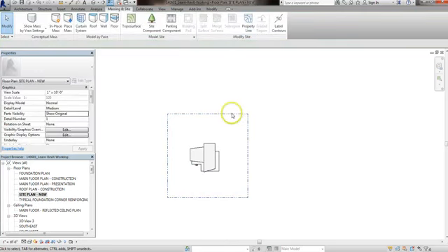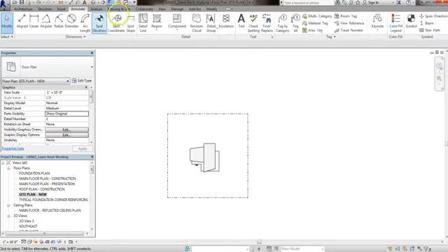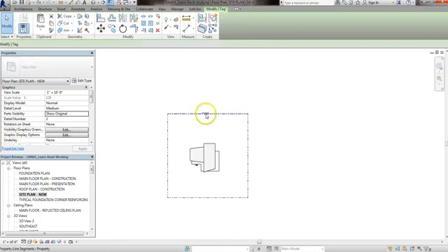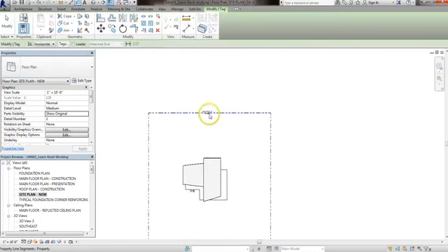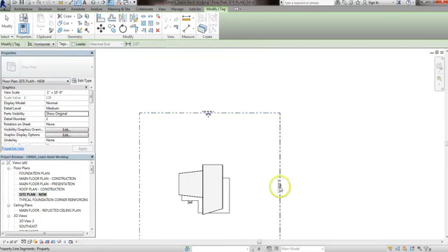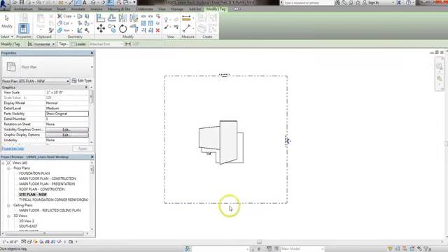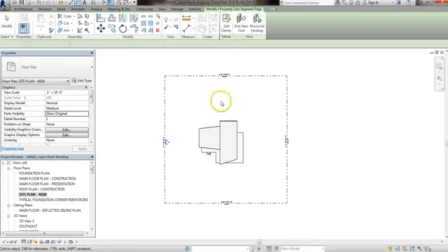So now we have our property lines. And then we're going to annotate them. We're going to tag them. We don't need the leader. Now I can tag them. So if you guys had the survey and we're doing it by them, once you tag them, they should match up with the surveyors. Perfect.